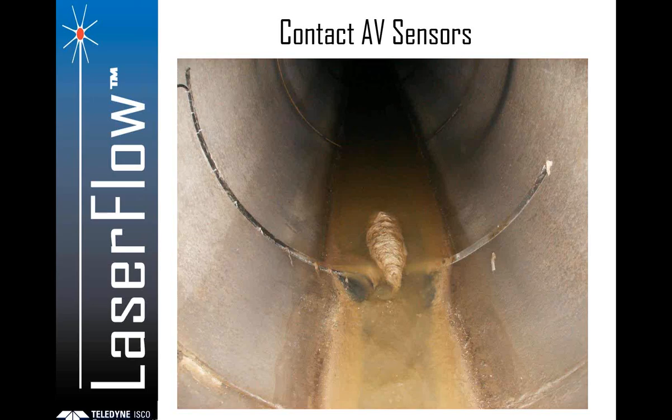Now, in those meters, we do have some technology or some features to deal with that. We call it flow rate 2, where basically you can have the flow rate based on the Manning equation, even if you don't know the slope or roughness coefficients of the channel. We can use some features in our FlowLink software.